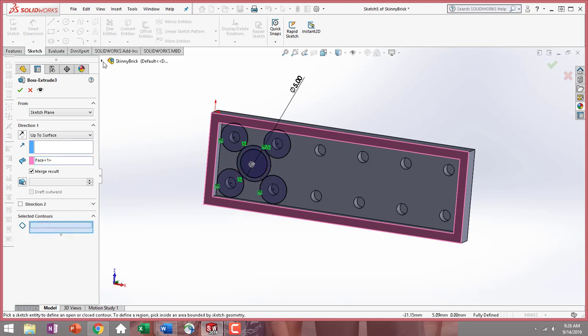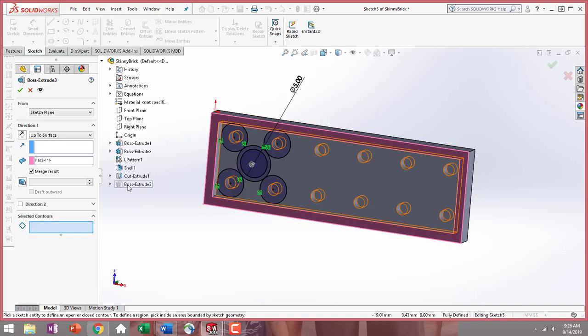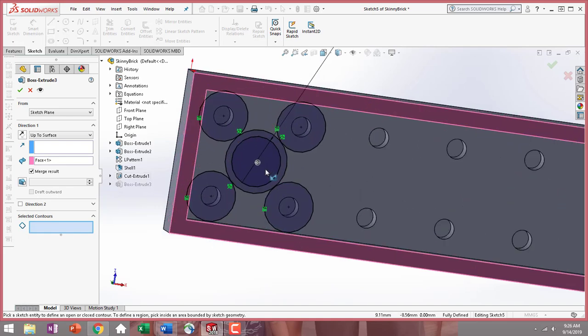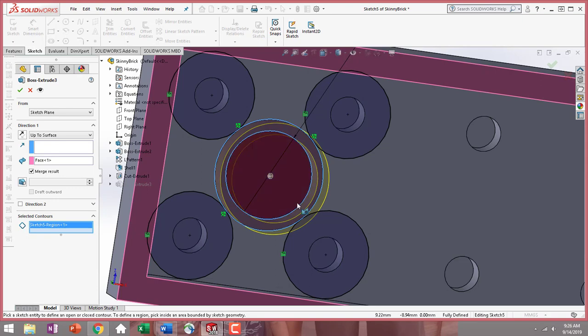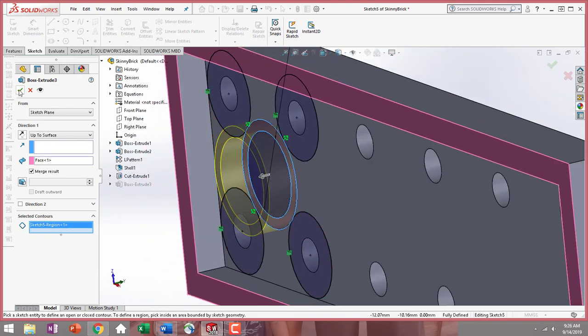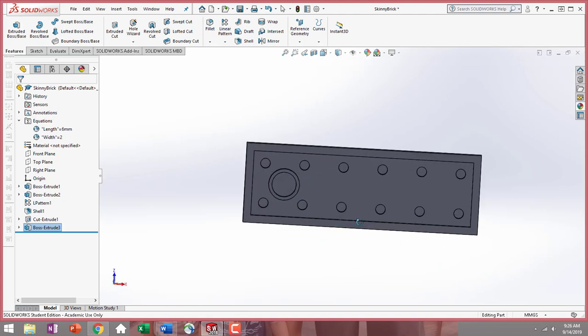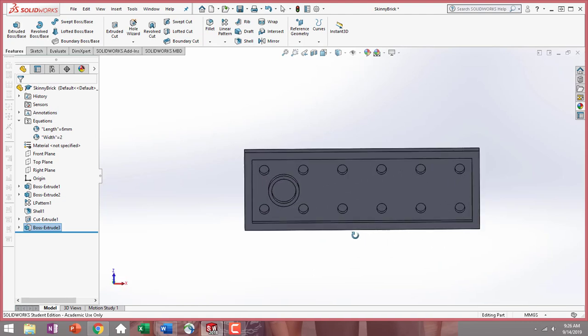You can come up here and select this arrow over, and you're able to select your face there. Or you can zoom in, and I'm doing that by rolling my roller on my mouse. So before I only selected this outer edge, so that whole extrude was that whole diameter. I want only the material between my two circles because this is a hollow circle under our Lego pieces. So select it, and then you can see a preview of that annulus. Go ahead and hit OK. So now we have our bottom feature. That's what it should look like. It's just a thin material all the way around.